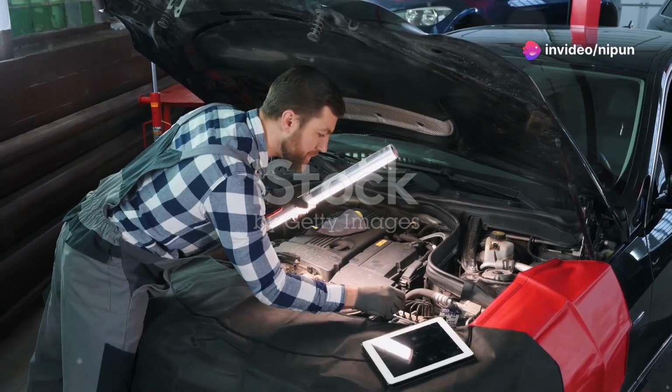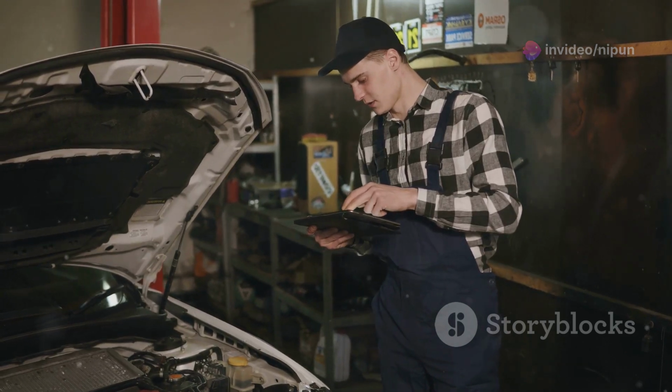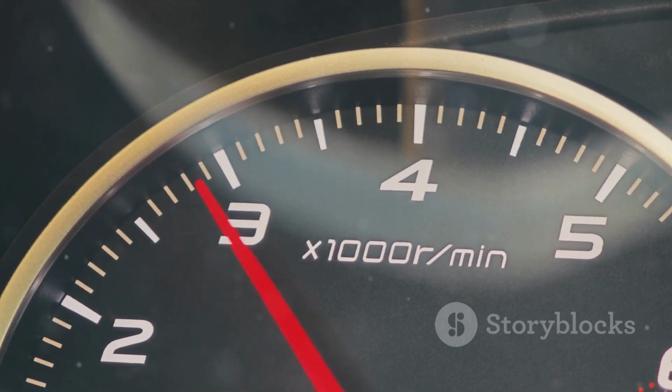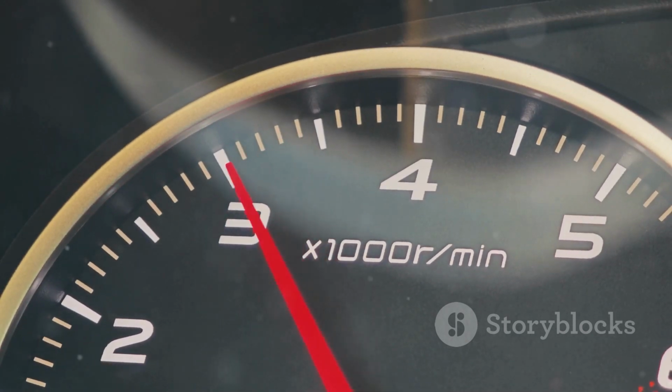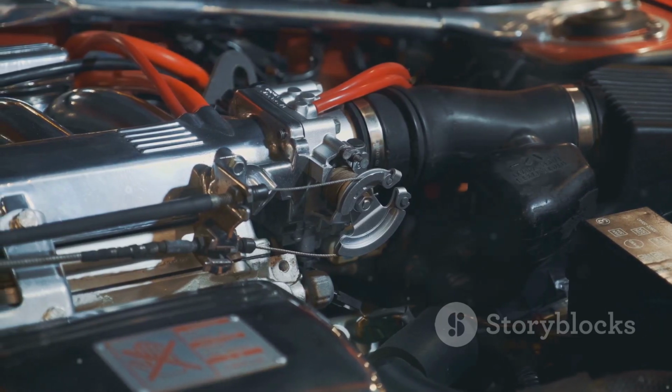By analyzing the engine's performance under full throttle, technicians can identify potential issues. For example, if power and torque are significantly lower than expected at a certain RPM range, it could indicate problems with the ignition system, fuel delivery, or air intake.